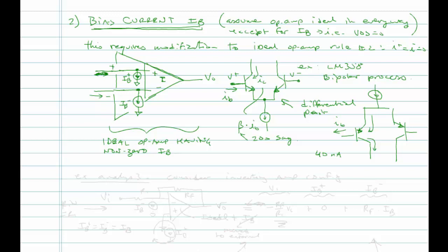All right, so that is going to be consistent, because ultimately the polarity of those bias currents is going to be a function of the actual circuit topology inside the op-amp, the implementation. Fortunately, because of the ability to represent the internals by some simple element, in this case two independent current sources, we don't really have to worry about what's going on inside the op-amp and the transistor differential pair or anything like that.